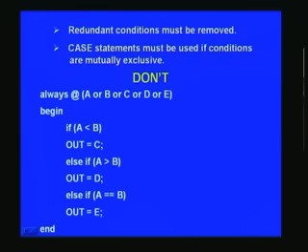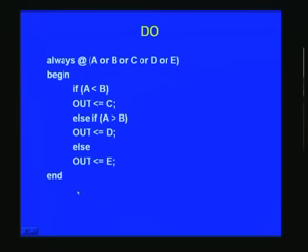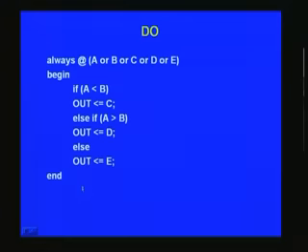So, now is there any other possibility? The solution is simple, and you can dispense with one of the muxes. This is precisely the same, and after A equal to B, D is assigned, 2 muxes already present in service. Now we know that when we come to this step, it is already A equal to B. So, instead of putting else if, you just put else, and then E can be straight away assigned here. By doing so, notice that else if combined with else both means a single mux only, as we have seen earlier also, and that is how we save one mux and thereby improve the speed of operation.